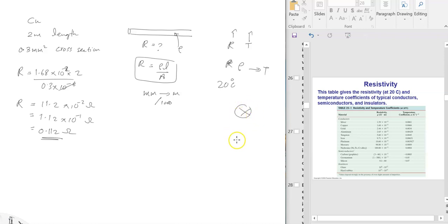The physical structure of a light bulb looks like this: the glass area, the metal connection, and here there's a metal coil. This is made out of nichrome. When current goes through it, because of the high resistivity, it heats up, and that's what we get as light.